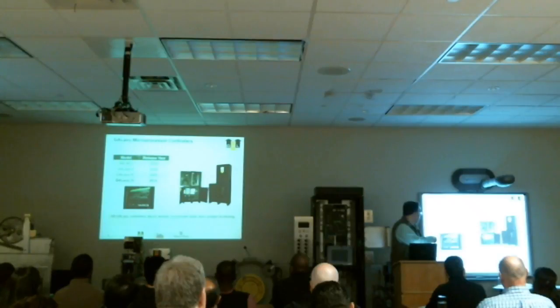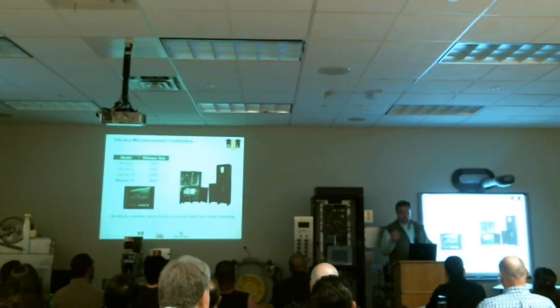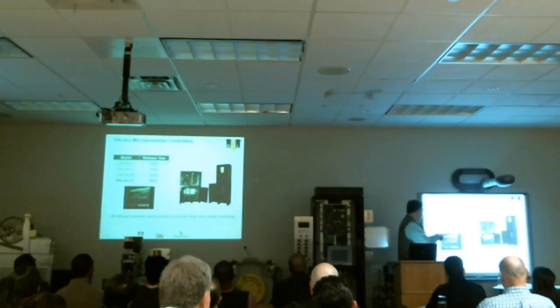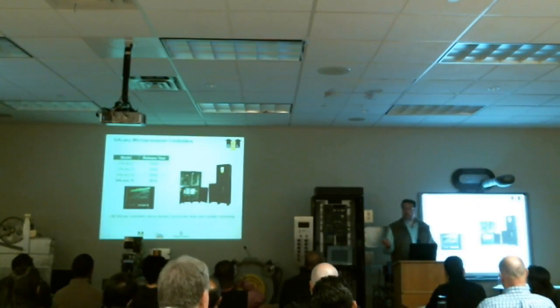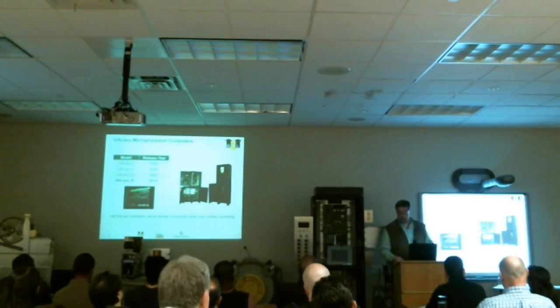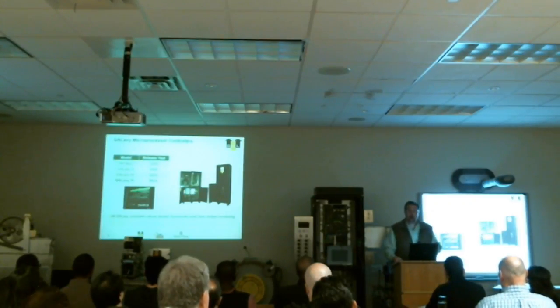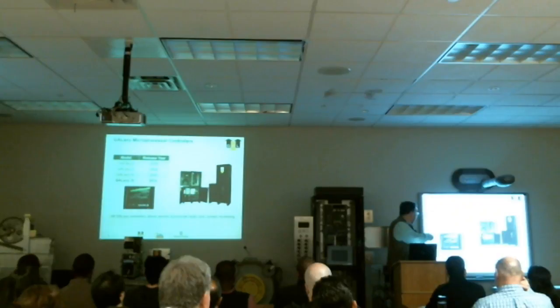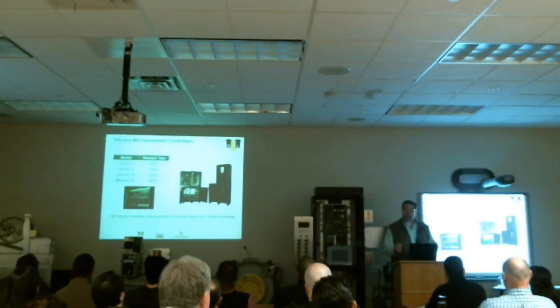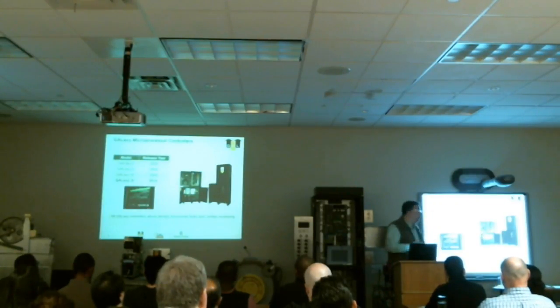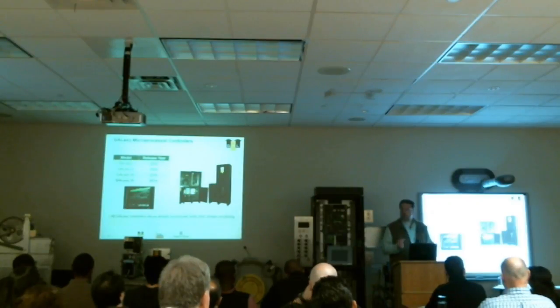Now, mind you, Galaxy 1 and 2 already have door lock monitoring in place. Okay. We've already had them in place where we can monitor, and if anybody detects a bypass gate, we shut the elevator down. The problem with the component that we don't comply with is the fire service compliance for New York City. That needs to be added. But Galaxy 3 and 4 are software upgrades on older jobs, again, that have door lock monitoring that we've had, but don't have the fire service phase 2 component of that.